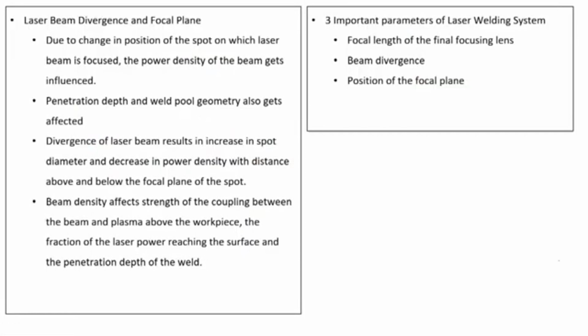Now, as far as the beam divergence and focal plane are concerned, due to a change in position of the spot on which the laser beam is focused, the power density of the beam gets influenced. As the laser beam focusing is changed, it is affecting the power density. The focal plane is to be set properly based upon the requirement. If you want to have more intense localized temperature, then the focusing should be very accurate, and in case of heating up the workpiece, then we can even have a diverged laser beam on the work part.